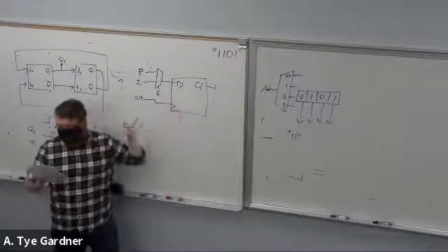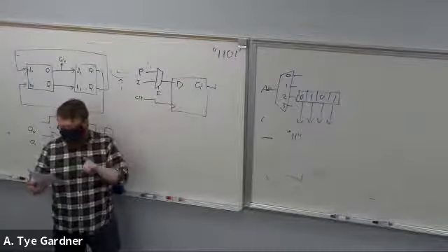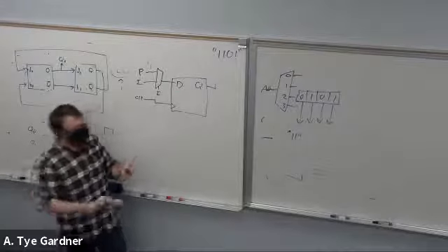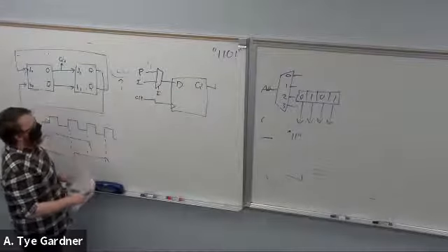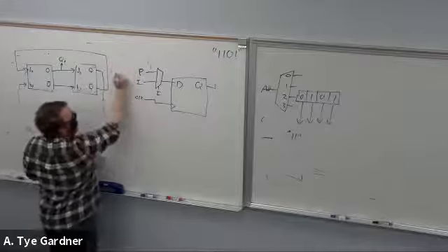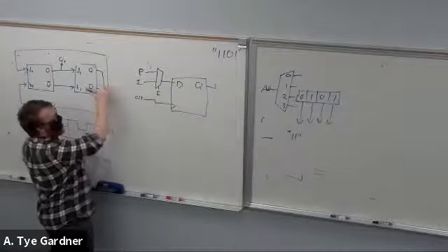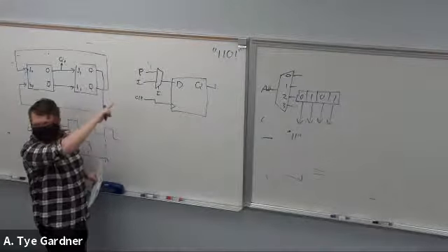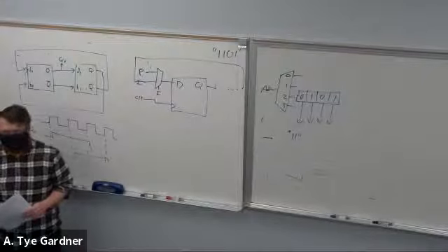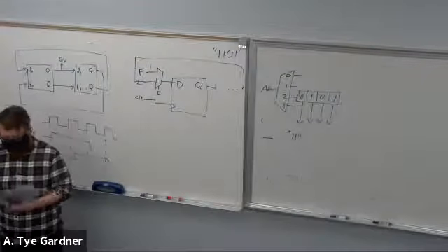And then the other part of that is to make sure the contents of the shift register change from 101 to 011. Now, there's 2 ways that you could have done this. No one did the first way, which is good, which is you could have drawn another shift register on the first flip-flop that had the correct contents in it and shifted it in. The right way is at the end of the shift register, you just tie it back around to the input, right? So it becomes a barrel shifter that we like to talk about.